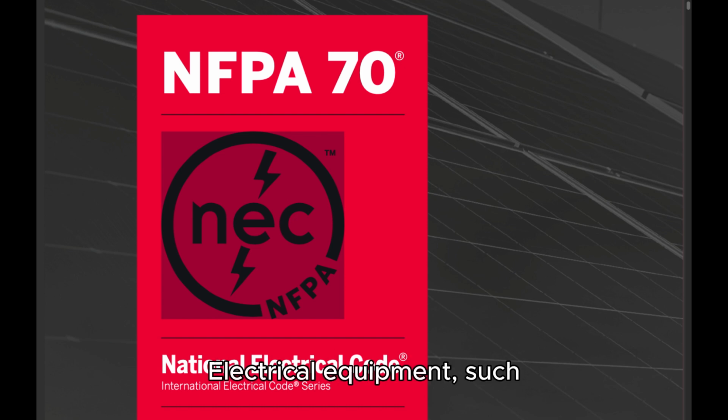110.16 Arc-flash hazard warning. A. General. Electrical equipment such as switchboards, switchgear, panelboards, industrial control panels, meter socket enclosures, and motor control centers that is in other than dwelling units and is likely to require examination, adjustment, servicing, or maintenance while energized shall be field or factory marked to warn qualified persons of potential electric arc-flash hazards. The marking shall meet the requirements in 110.21(B) and shall be located so as to be clearly visible to qualified persons before examination, adjustment, servicing, or maintenance of the equipment.